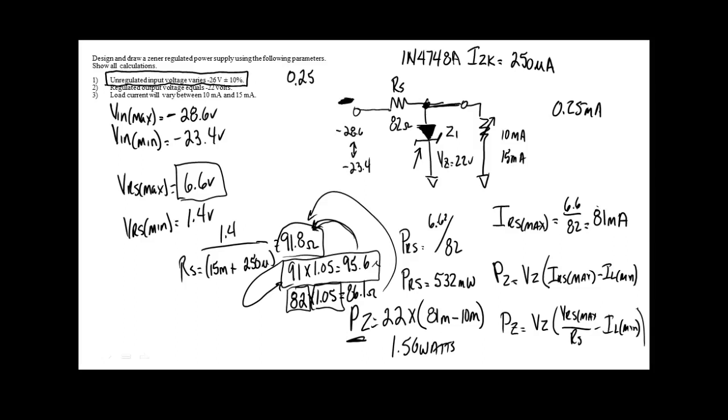What'd you say? I'd change the Zener. That's exactly right. I'd find a 2 watt Zener. I'd go on the internet and search for a 2 watt Zener, and it would pop up a part number for me, and that's the one I would use. You understand?